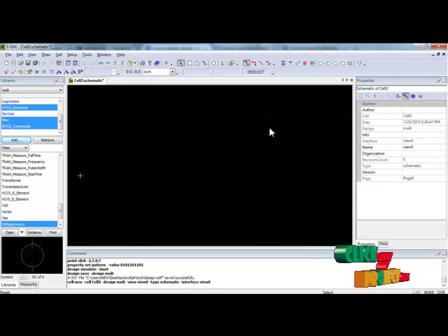So, we can design the circuit based on CMOS transistors by using SEdit. Before we start the simulation, we have to select a new cell. Here is the cell menu. Here we select the cell menu and select new cell. There you can select a number of cells, like cell 0, cell 1, up to cell n. Each cell should contain a different CMOS design.